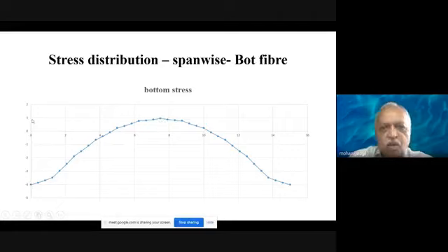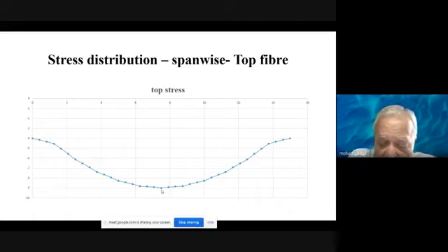Now you can conclude easily that the maximum compressive stress that you are getting is about 9 for M35 grade concrete, which is permissible. Normally about 0.35 of the grade of concrete. So if it is M35, and if you want to consider compressive stress, then normally you will be able to go up to 10 Newton per mm square, because 0.3 to 0.35 of fck, you will be able to restrict the compressive stress. So that will be limited to 10 or 11, and you are within limit.